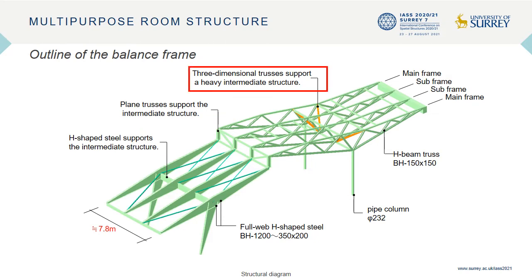The orthogonal beams in the sports forum section are also trusses because of the heavy weight of the concrete slab and plantings, and the orthogonal trusses are made into three-dimensional trusses in accordance with the lattice shape of the main truss structures.